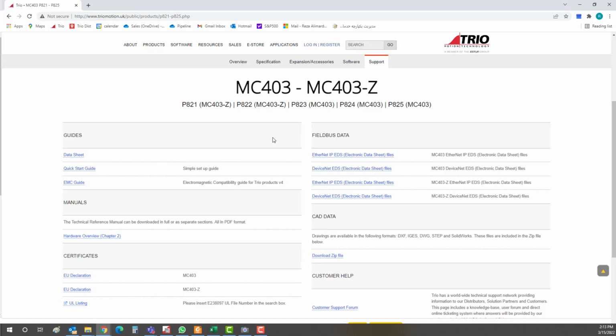Now I'm not talking about the mapping for accessing the VR variables. That's a different topic. We always keep that standard. You can access through Ethernet IP at address 4000, so VR0 is mapped to the address 4000. Let me show you.